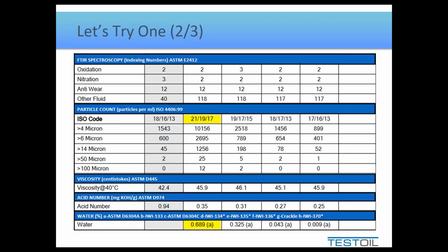So though you might lean towards saying that the particle count is a cause because it should be effects of that lead, iron, and silicon, I'm going to assign it definitely in the cause column. So I've got high silicon and I've got high particle count as causes.